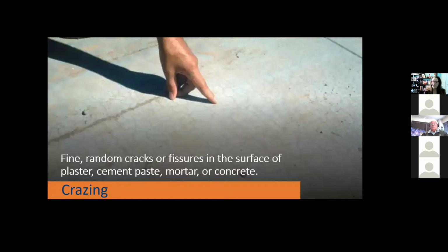Another thing that happens very commonly in concrete is crazing. I've heard people say that crazing is a finishing issue. It means that you've over-troweled the surface. I would disagree. I think the most common reason for crazing is that you have rapid surface evaporation of the mortar. And so what it really is a problem of is what George talked about last week. It's a curing issue. You did not use any initial curing.